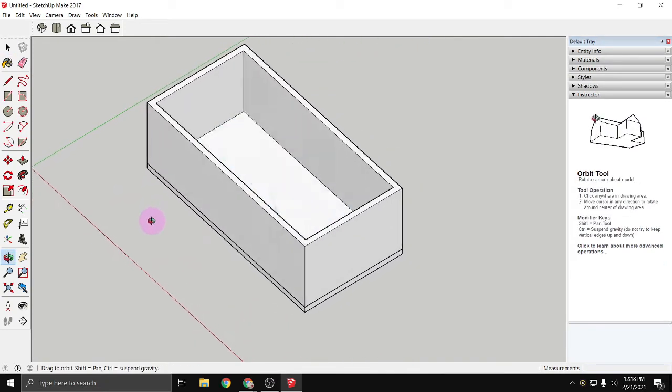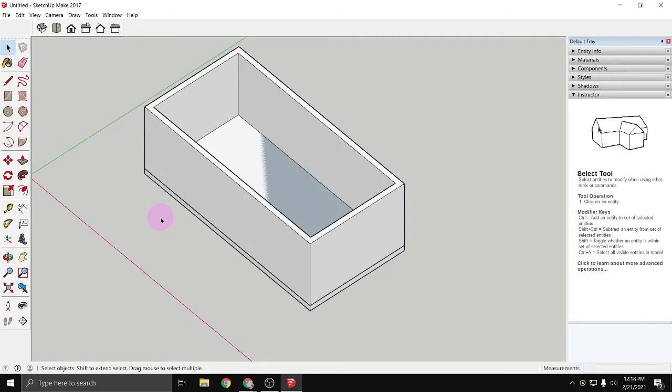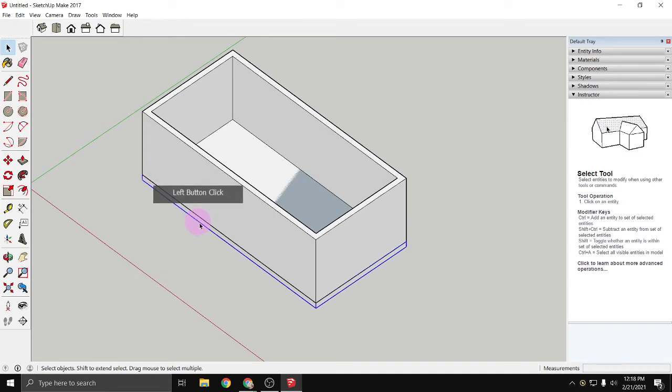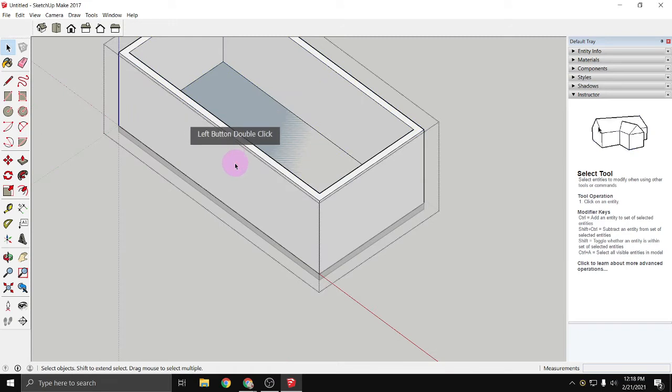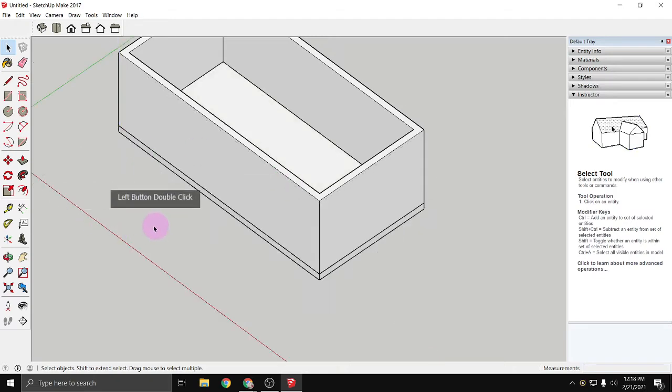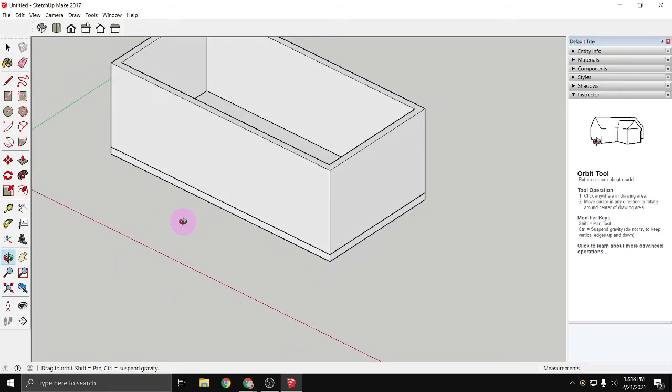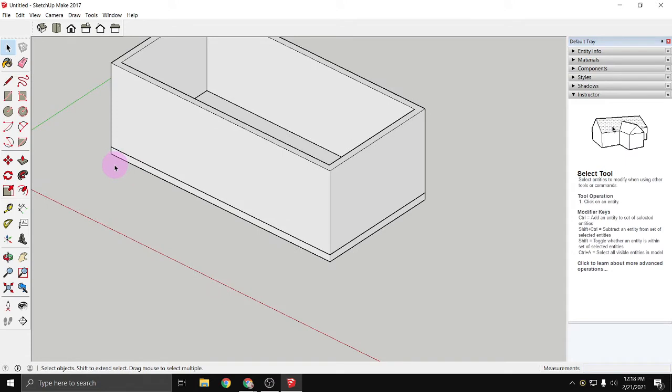And right now what I can see, and it looks like to me in OBS it's popping up, which is good, is that we have the face of my floor and the bottom of my walls, they're kind of glitching together. And so that's when I can go and double click on my walls. I can click on that face there and I can delete it, double click outside of it. So you can kind of edit things as you go, but it's just always a good idea to keep things in groups as you are making it.